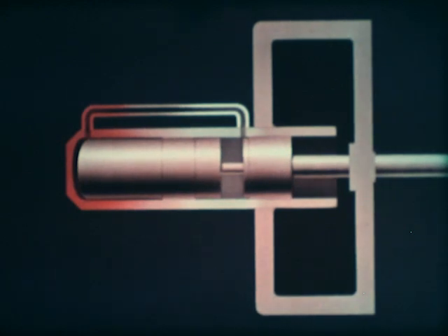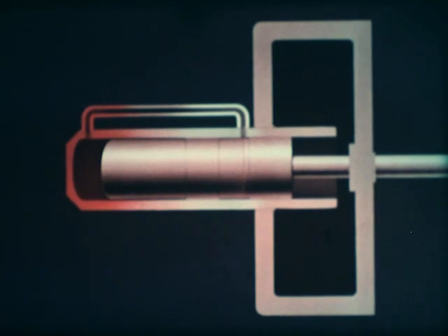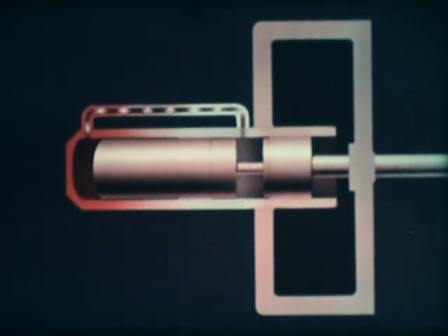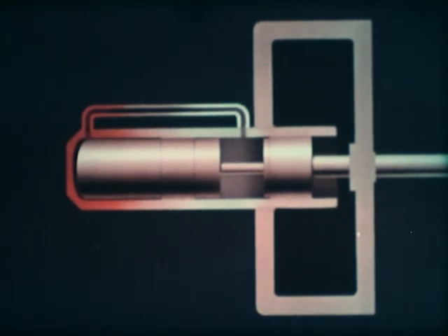The cylinder head can now be kept constantly at a high temperature and the other end at a low temperature. The whole cycle can be performed without wasting heat energy on the cylinder wall. First, the gas is displaced to the cylinder head where it is heated. The gas is then expanded and work is done on the power piston. The gas is driven to the right and therefore cooled. And again work is done due to the pressure in the buffer space being momentarily higher.